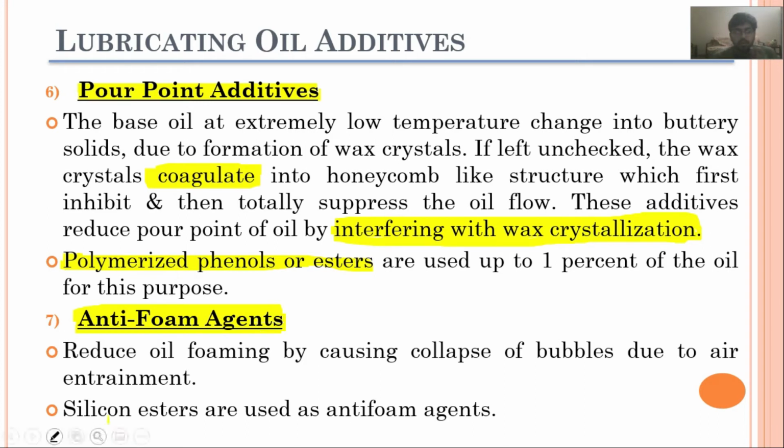If we do not add these additives, foaming will start, and the air bubbles will accumulate in the lubrication oil, and when these air bubbles burst, the air will start contacting the metallic surfaces of your IC engine, and they can start wear and tear, and the formation of rusting as well.